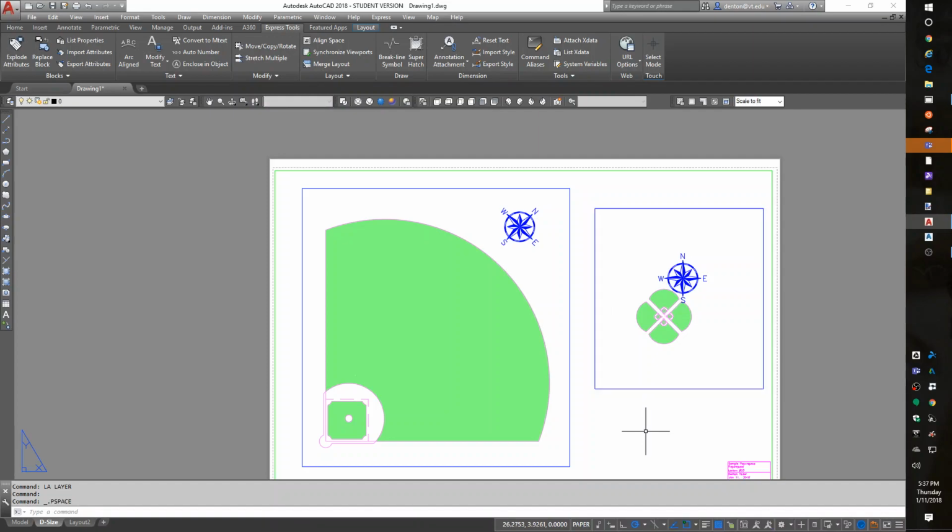So what we're seeing is that layers are independent to some extent in each mview. So each mview will keep separate track of the viewport freeze. You can also change colors and line types in the different viewports. So you can force things to be proposed in one view and be bright, and be a thin dark line as existing in a second mview. So that's your choice.